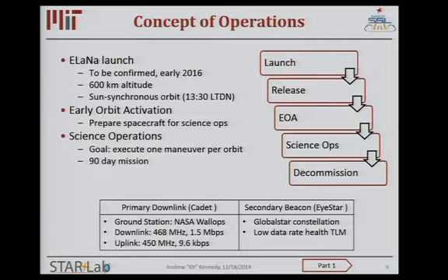While we're stowed on board the rocket that will release us, the spacecraft is not on. And we have an early orbit activation phase where, after we deploy from the rocket, the flight software turns on, and then we have to wait for 45 minutes before we can actually start communicating and deploy solar panels. This is standard for the way CubeSats work. They have that limitation. And then we start our science operations.